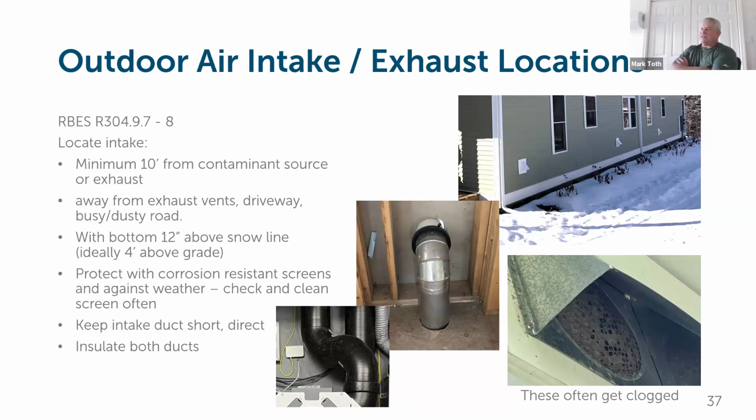So this is not always an easy thing, and it's not an easy thing to talk to a homeowner that's building a brand new home. We tell them we have to cut two 6-inch or two 8-inch holes in the side of their house somewhere. And they may right off the bat say, it can't go in the front. There's no way it can go in the front. Well, maybe the front is the only place where you can get fresh air because of other exhausts or the grade or whatever it is. So it is definitely something that needs to be talked about and taken into consideration. So next one.